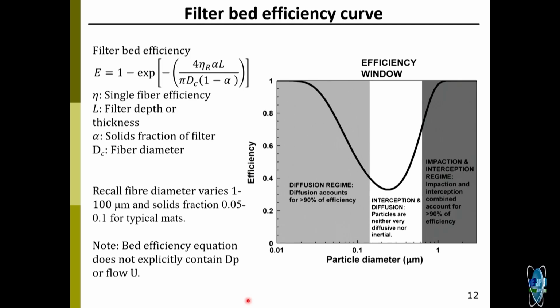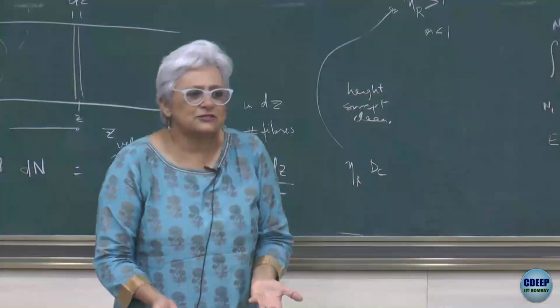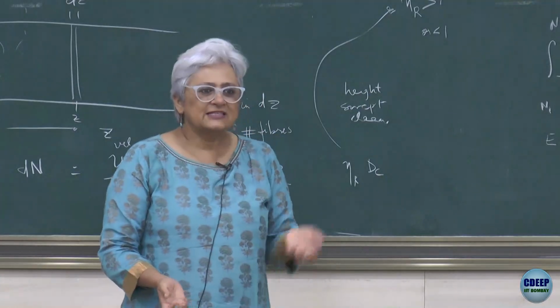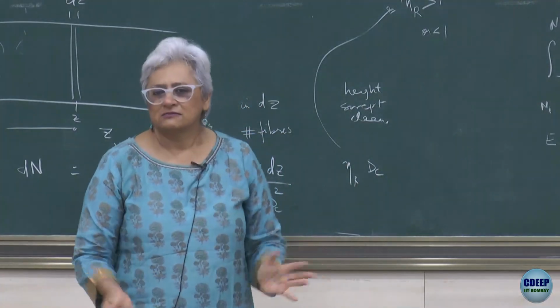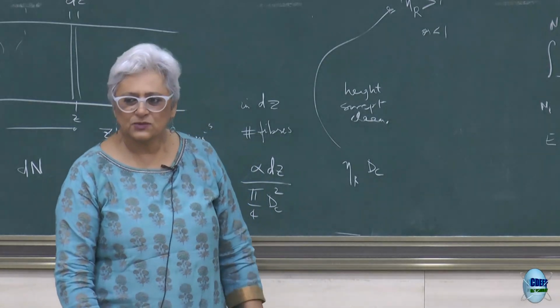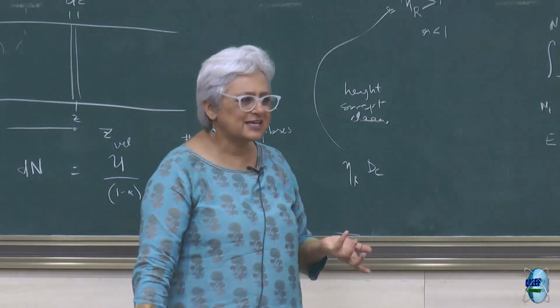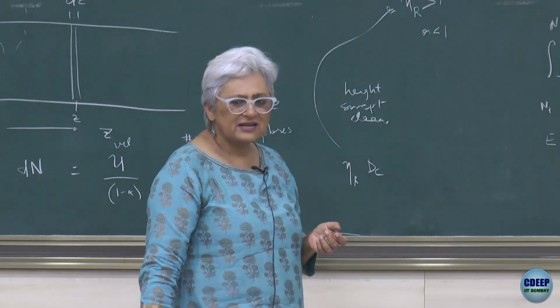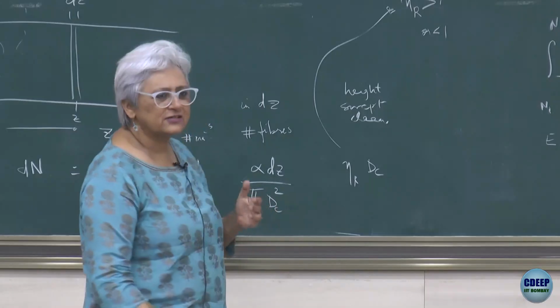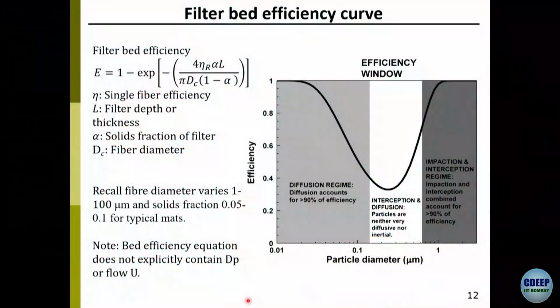It's neither diffusive enough nor inertial enough, right? So the particle itself is not able to do anything. It has to rely on the fluid to bring it to the collector, otherwise it does not get collected. It is really a particle that does not have any ability to arrive at a collector by itself, right? So that is this idea of the minimum deposition efficiency corresponding to those particles.